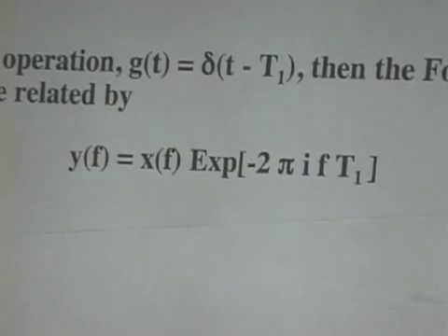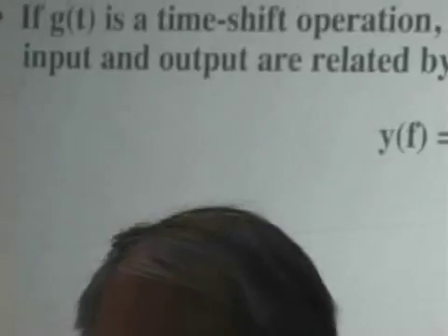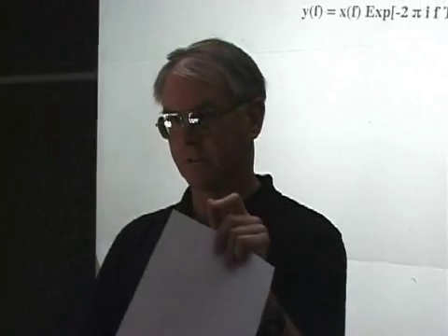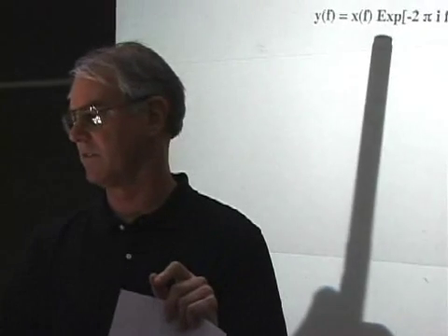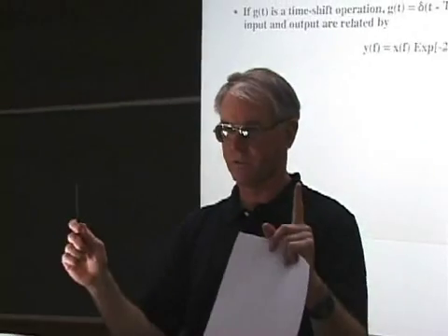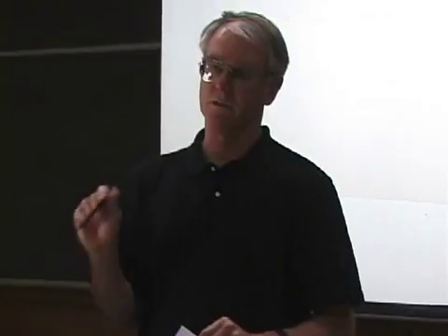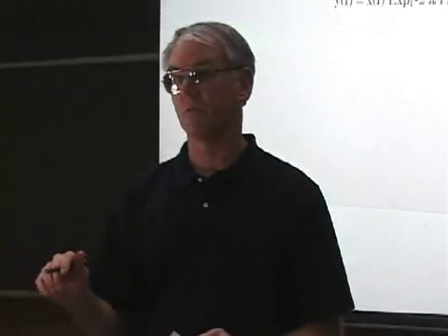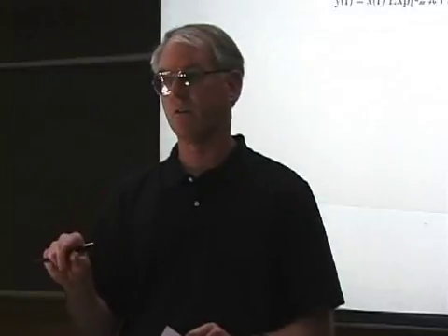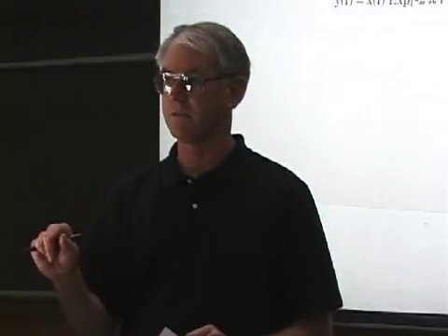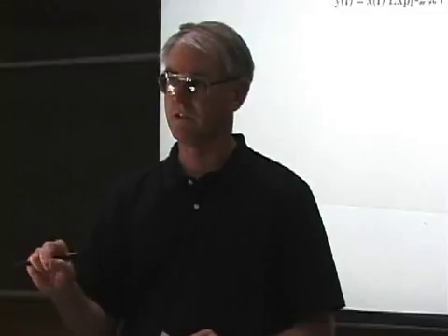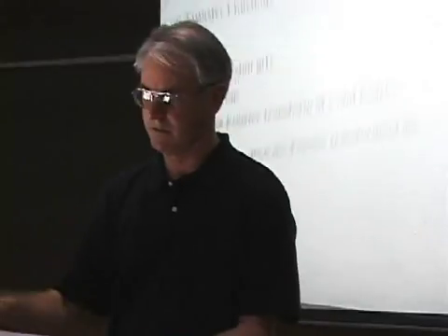So if you take the difference of the data at time now minus the time elsewhere, in the Fourier transform domain, you're going to get a delta function from the first one, and you're going to get a delta function times e to the i 2 pi f offset in the other one. You take that complex number, square it, and that gives you the spectral modulation of that particular noise source. And that's all I'm going to do in the next few minutes, to walk through two examples to show how you can calculate, if you were so inclined, the spectra of the noises of any of these things in a very simple way.